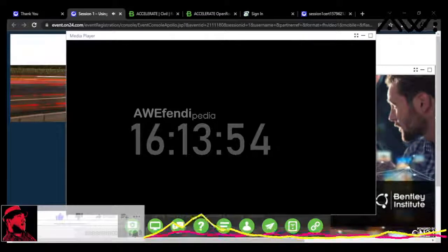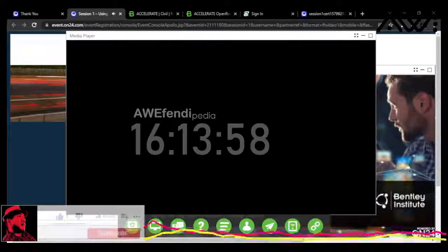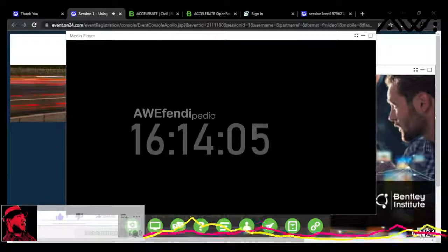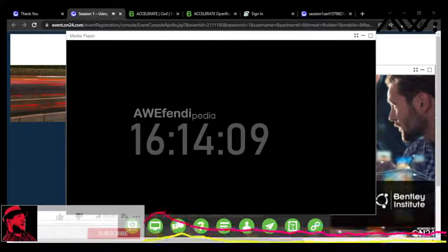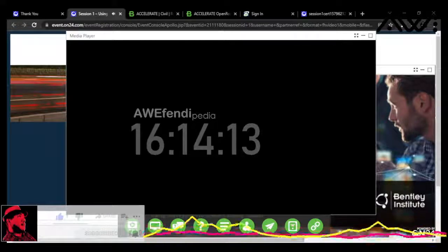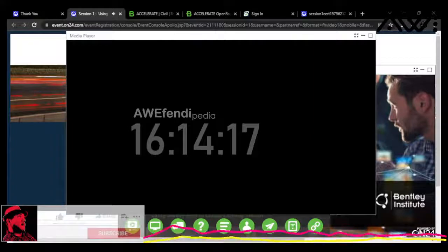So what I'm actually going to do to fix that up, I'm just going to give them new string numbers. So I'm going to come up to this first point here on this side of the driveway. I'm going to go to its properties, and I'm going to change its field code, and we'll call this one 7. I'll type in a 7 there after the field code, alpha code, and hit enter on my keyboard. That's going to change that.